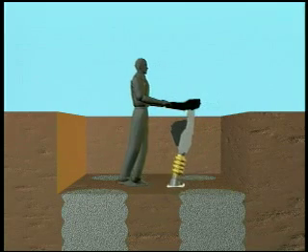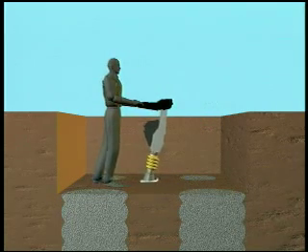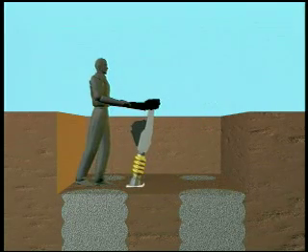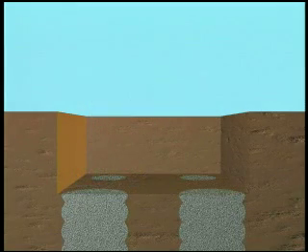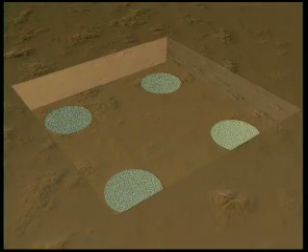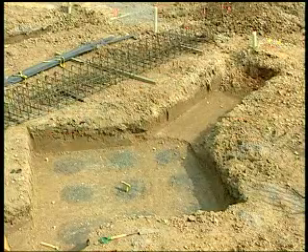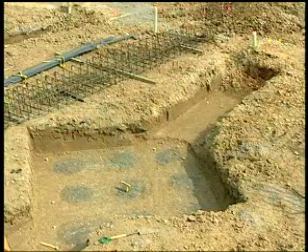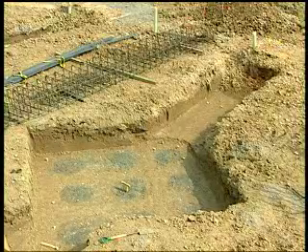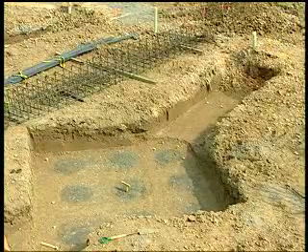The process takes very limited time, perhaps 2 or 3 minutes for a 10-foot square footing. The compacted pier top and footing bottom should be inspected and approved in writing by the geotechnical engineering firm representing the owner. Percent compactions are not required. What is required is a verification that reasonable impact compacting energy was applied, and that the Geopier tops and footing bottoms are not weakened by saturation.